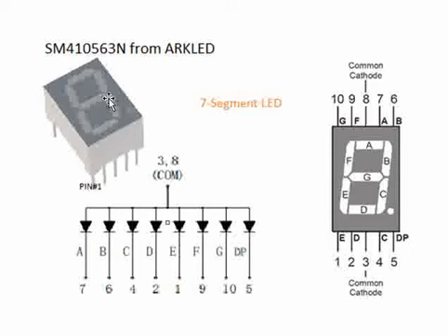Now, if you see the 7-segment display here, there are pinouts from this display, starting from 1, 2, 3, 4, 5, and then 6, 7, 8, 9, 10. In these 7-segment displays, there are 2 types. One is called a common cathode configuration, and the second one is called the common anode configuration. The one you see here is a common anode configuration. You can see all the anodes of the LEDs inside are common, so that is why it is called common anode configuration.